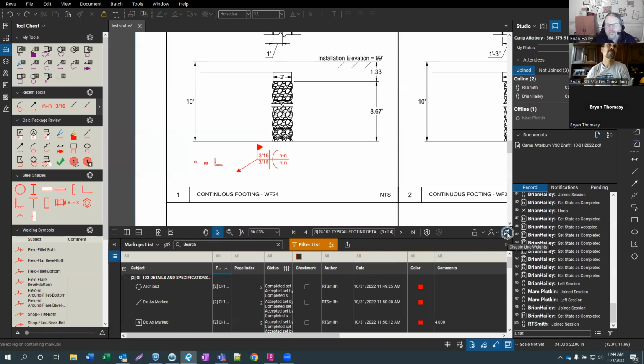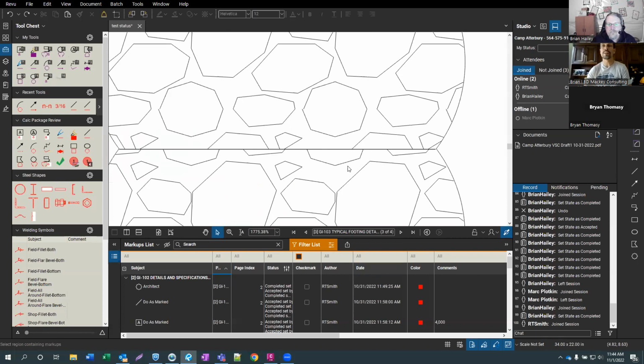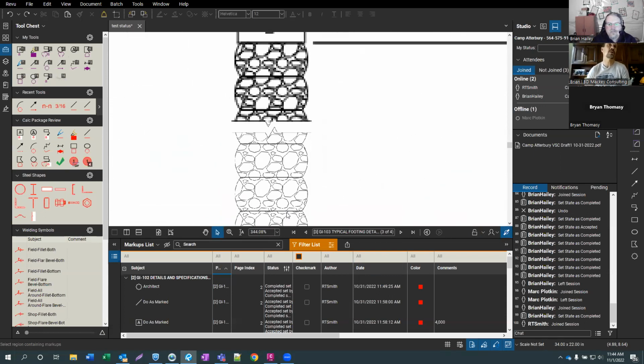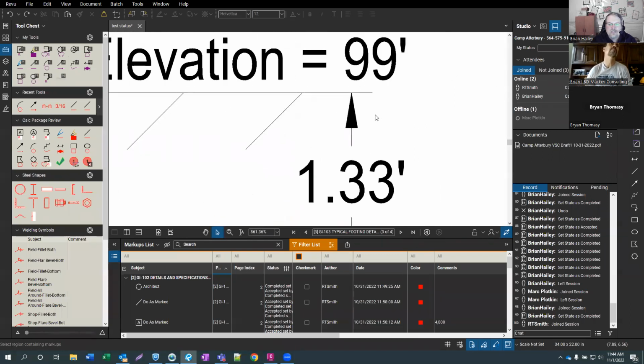It's right here too. I don't think it's there in mine. Did you add it there? Because I'm pretty sure it's not there in mine. Yeah, that's one thing I don't think everybody realizes, that you can just disable line weights, which helps a lot when you're trying to place dimensions or something. Yep. You're like, did I get to the end point of that line? Because the lines are so fat, you have no idea.